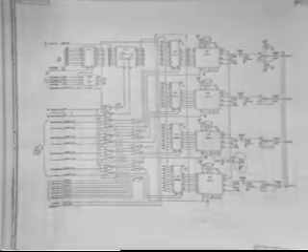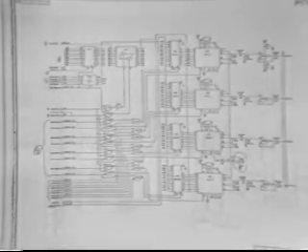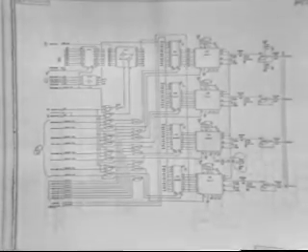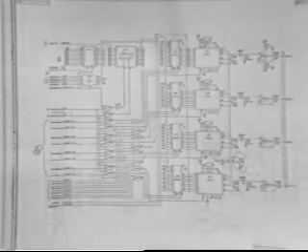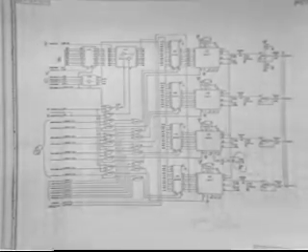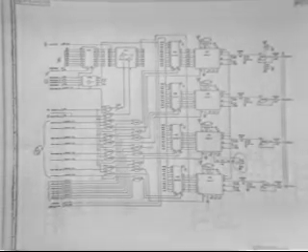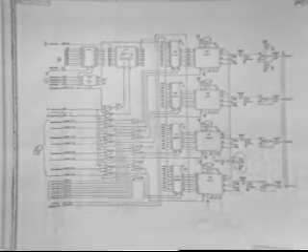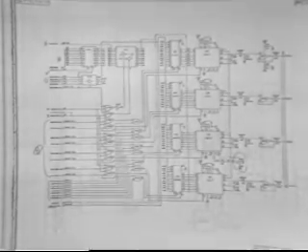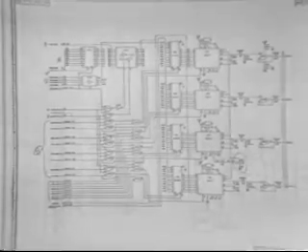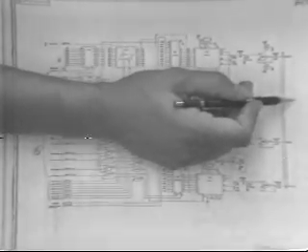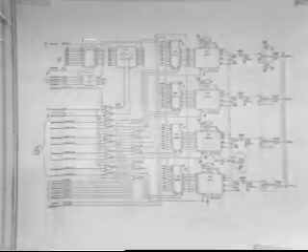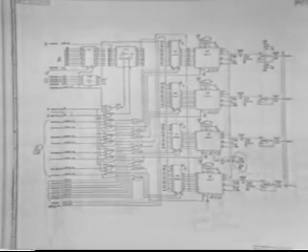When the microprocessor is in idle state, our output is 2.6 volts DC, plus or minus 0.13 volts. And when we're in a test mode, what do we get here? We get a 2.5 hertz sawtooth. A 2.5 hertz sawtooth outputs in test mode.